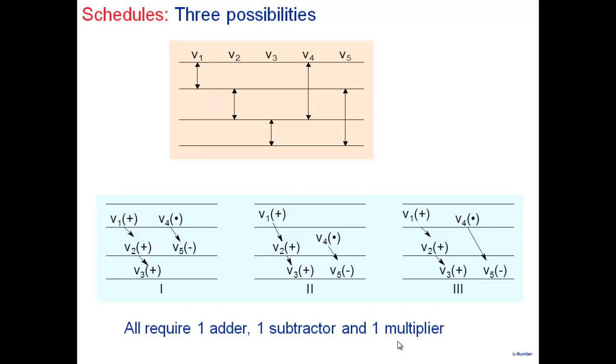Remember what you are doing? You are going from one register to the next register, right? You're taking the output of some register, going through some adder multiplier block, and then storing the result again in a register. So it's a register to register delay. That's what we saw. And for the timing, if you forget about the register delays, clock to queue delay and setup time and all that, and think about adder and subtractors and all that have the maximum delay, then we